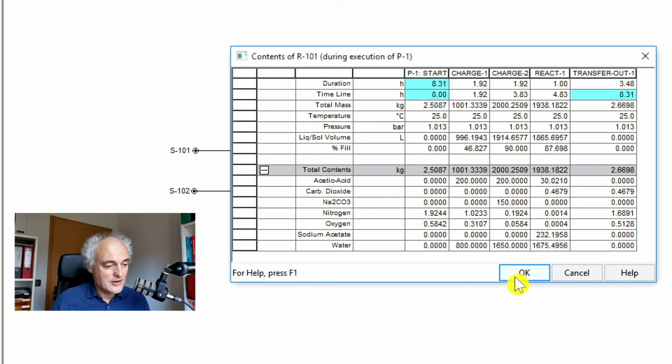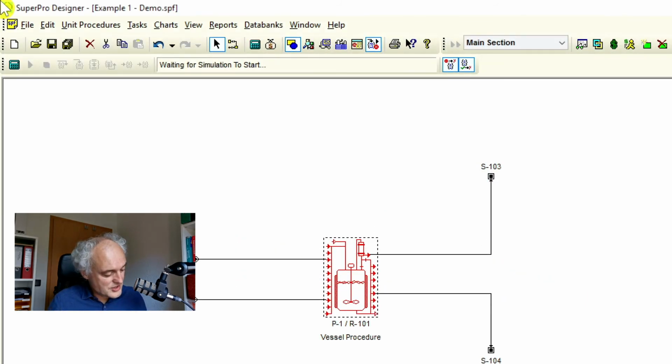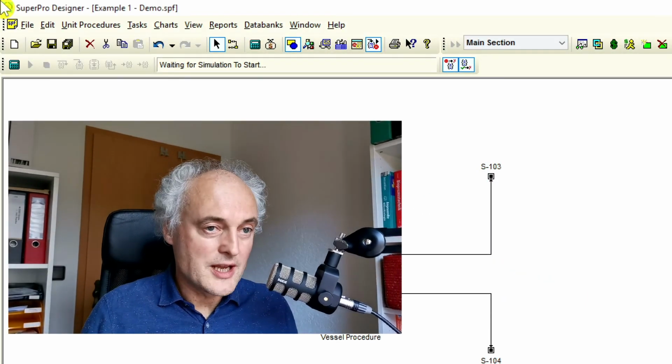Okay, now the next point is just mass flows. So at present, acetic acid is only partially neutralized. So of course, what you need to do is calculate how many. It's clear we have put in 1,000 kilograms of 20% acetic acid and 1,000 kilograms of 15% sodium carbonate. This would be luck if this would have neutralized equally. So what you do is you need to calculate yourself how much you need to pump in.